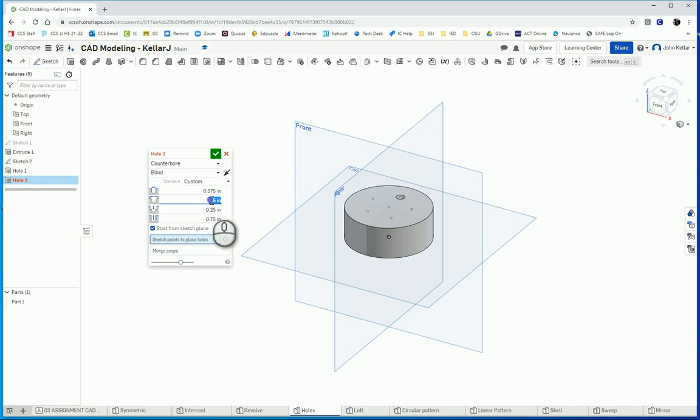Okay, then the major diameter to be 0.75. Then the recess to be 1/4 inch, and then the remainder of the hole down to a depth of 0.75. So that's from the top to the bottom of the hole to be 0.75. Notice it's going to be angled at the bottom, and we need to select where we want to do that. Notice it's got two holes in one. So you've got the recessed part that's wider, and then the actual hole if you look down in it.